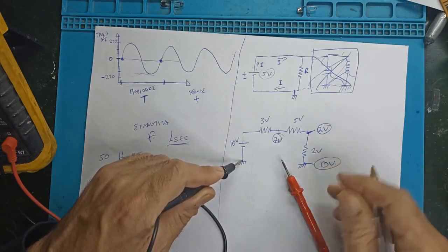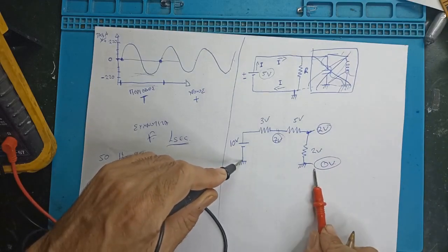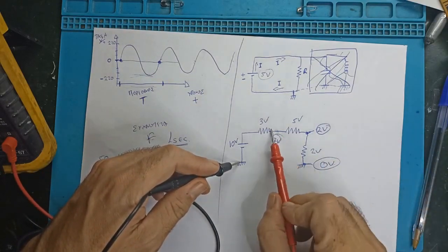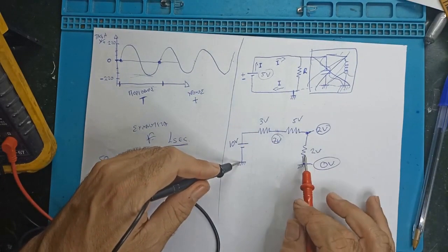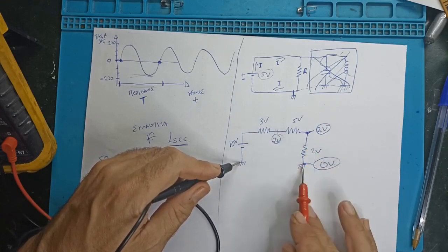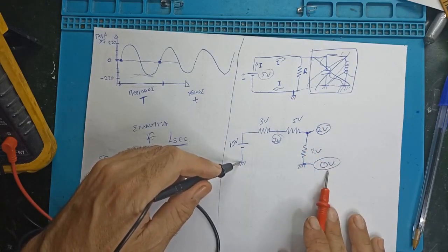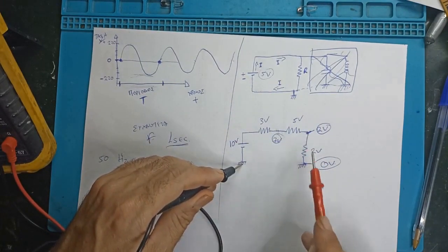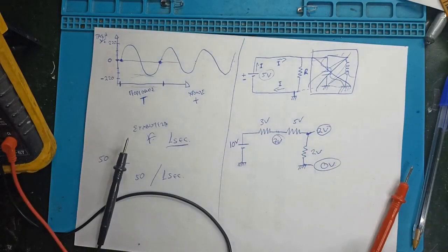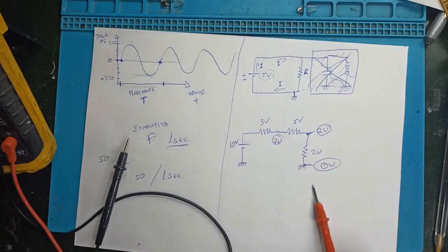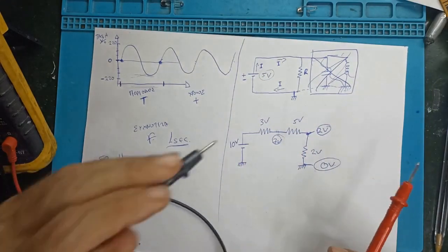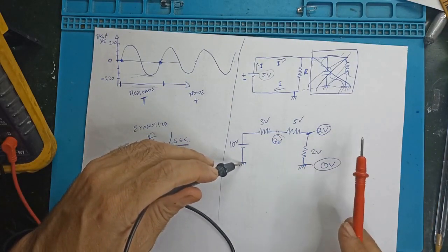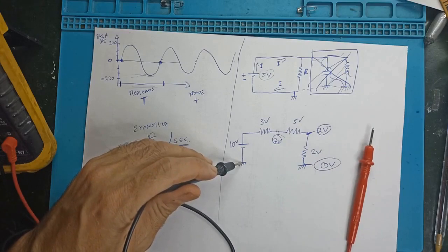And of course, visually, if we were looking at it now, we would see that the current is flowing through the resistors from plus to minus, so we have a flow of current whose intensity has been regulated by these resistors here, and not by the 10 volts of the source. So we said the current is regulated by the loads, which in this specific case are our resistors. And we said that in repairs we don't need to calculate the current. Someone else has calculated it for us.